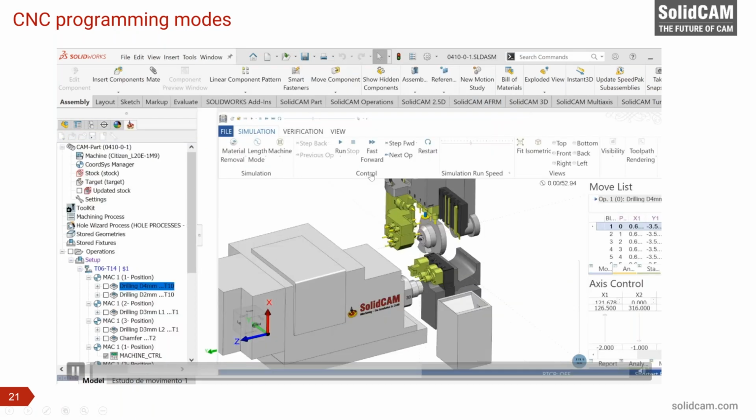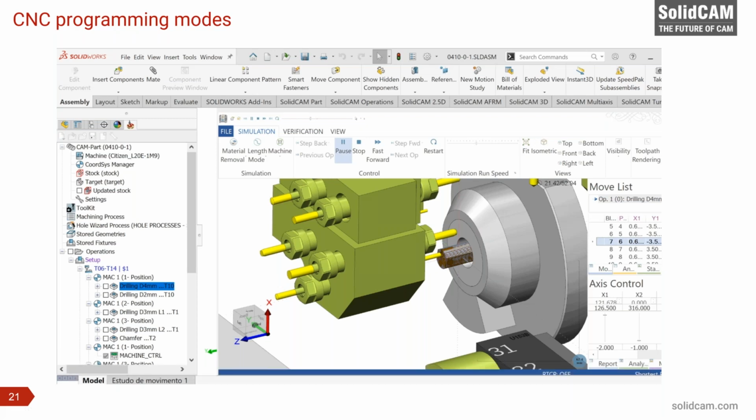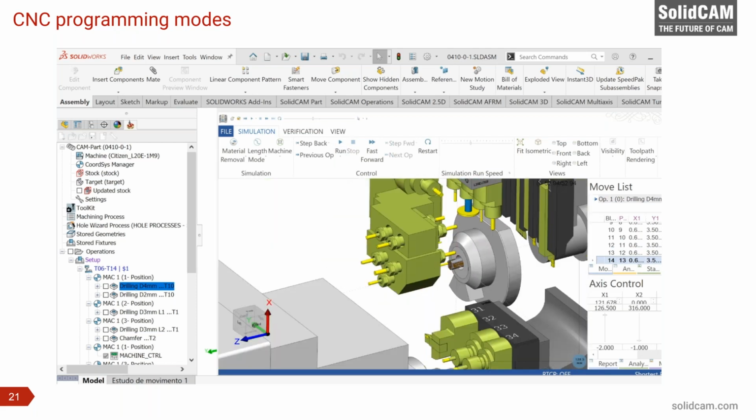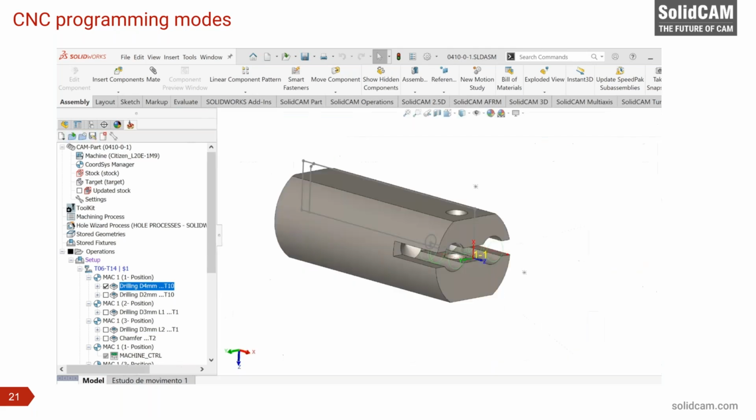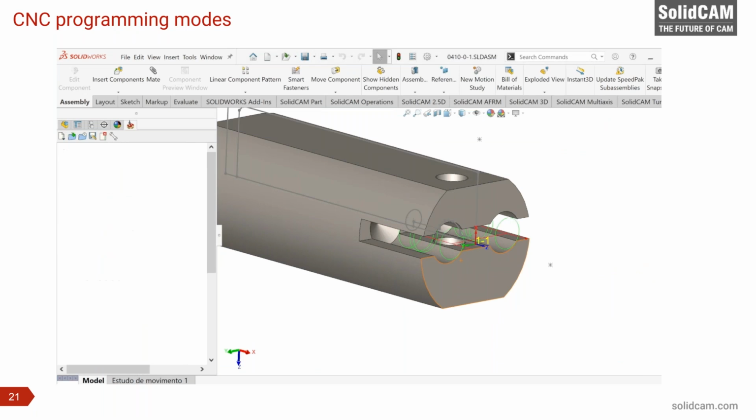So 4-axis, and it will output it with the C-axis. Just one click and you will have an absolutely different result. For the machine, it is critical because you may have limitations with the Y-axis, and you may need the C-axis to be implemented. Believe me, for some systems, it takes time to deal with this. But in SolidCAM, it comes with just one click.